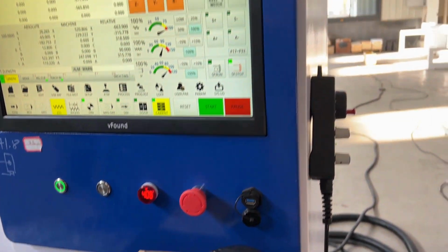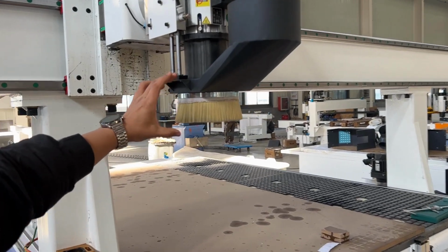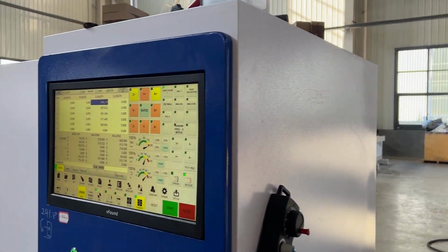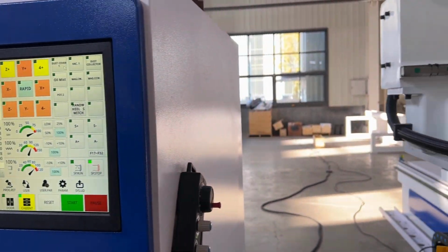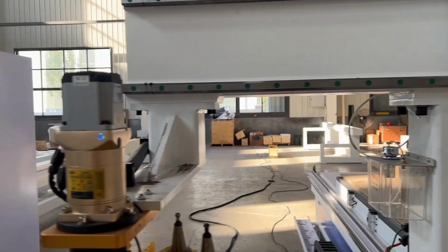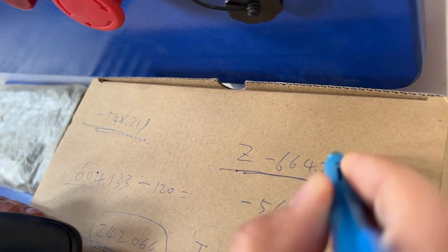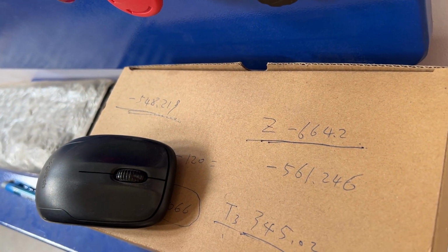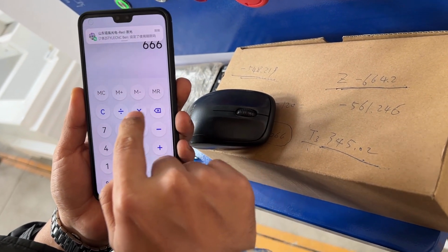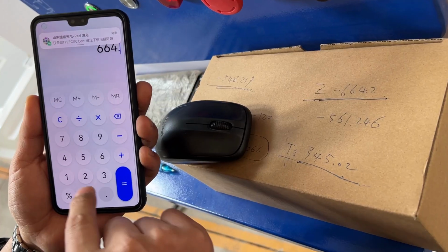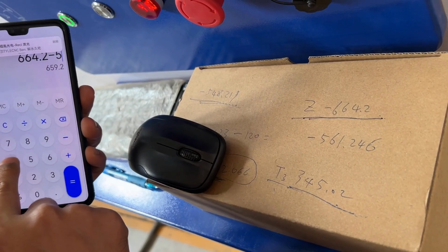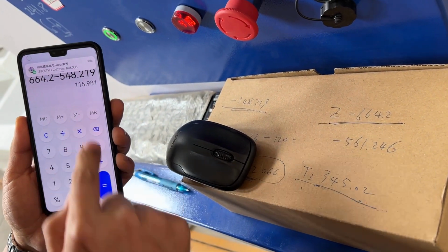We still need to record this length. The distance is fixed when there is no tool in the spindle. The data obtained from automatic measurement with a tool in the spindle is subtracted from this fixed distance to get the length of the single tool. Adding the length of the spindle to the length of the single tool gives the total length of that tool.